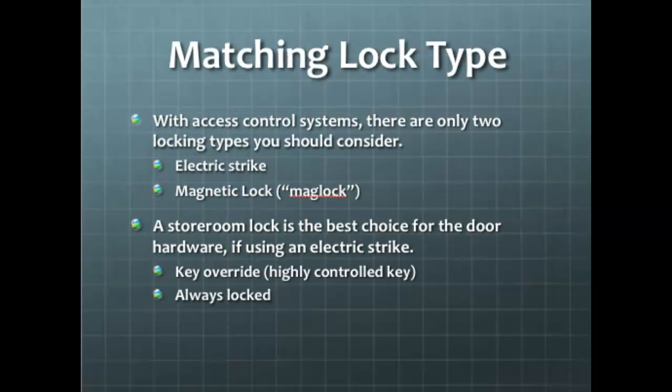So when it comes to access control systems, you have electric strikes and you have maglocks. But if you think about an electric strike, and something we hadn't really talked about until now, is that the strike itself moves, right? When you run your badge and it goes back to the panel and says, yep, Brian's good to go ahead and unlock that door, the actual latch on the door moves, right? The door frame kind of opens up, if you will, to allow that door to open. You still have to have some kind of a handle on that door. It can be just a fixed handle, right? It can be just something that doesn't turn. When that electric strike goes, you can pull it.